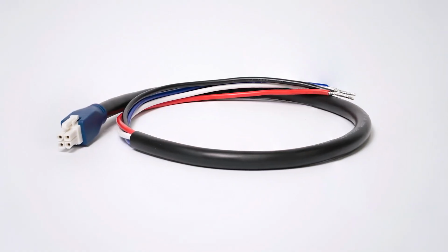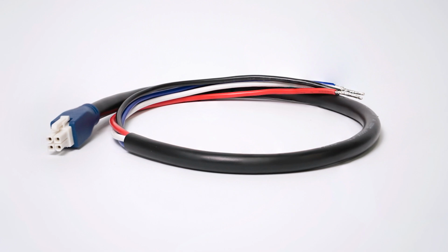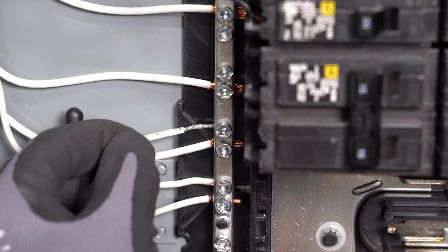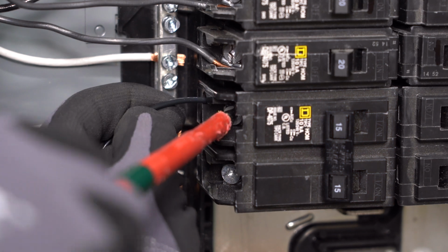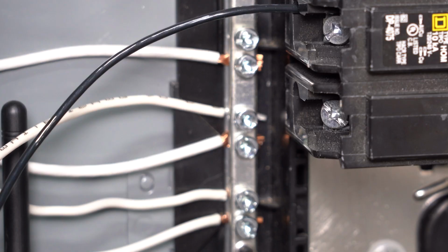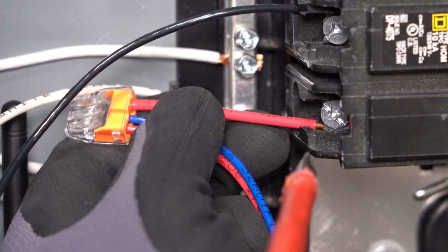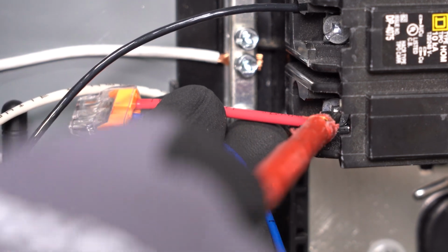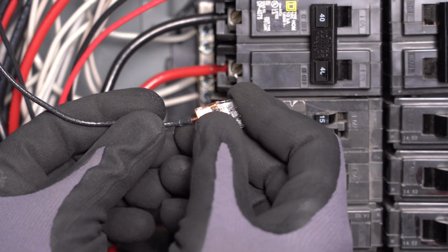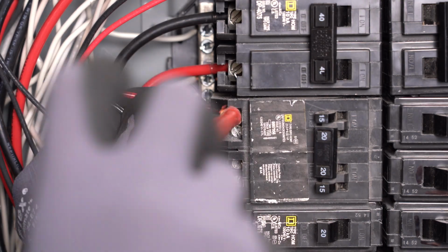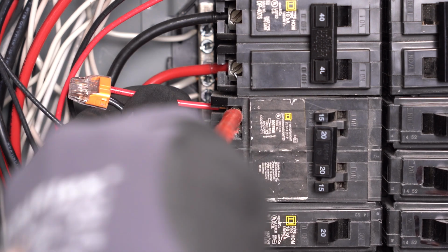The included voltage line harness provides both power and voltage reference to the meter. Land the white wire on the neutral bus bar. The remaining leads need to be terminated in a 15 or 20 amp 2-pole circuit breaker. Land the black lead on line 1 of the 2-pole breaker. Splice the red and blue leads together and use a pigtail to land them on phase 2 of the 2-pole breaker. If no new breaker space is available, use the provided jumper wires and taps to splice into an existing 15 or 20 amp breaker.